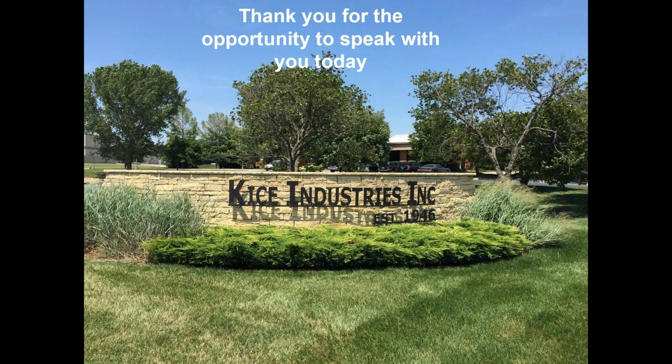And sometimes that becomes necessary when height restrictions come into play. Maybe we would like to put, for my example earlier, a 96 bag filter in with 10-foot bags. Well, we don't have that much headspace. What if we used a 96 bag filter and we put in 4-foot pleated cartridges? Believe it or not, a 4-foot cartridge is going to give you, I would guess, 2 to 3 times more filtration area than a 10-foot long filter sock. So pluses and minuses, largely dependent upon the industry.